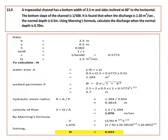So another problem of a trapezoidal channel, which has a bottom width of 2.5 but is inclined at 60 degrees to the horizontal. Again, same thing: tan theta is 1 by z, and tan 60, that is z is 1 by tan 60, which gives 0.5773. So this value is to be used for z. Similarly, b is given, y is given, and bed slope is given. So discharge is also given.